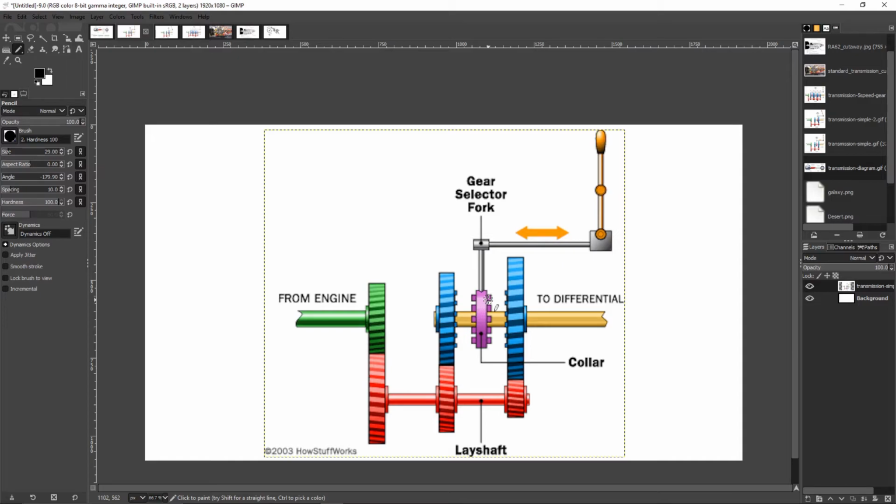The vehicle speed is determining what my output shaft is doing, right? So let's pretend that's this gear here, that's vehicle speed. I really can't change that. I could use the brakes to slow down, and that would change the output shaft speed. Engine speed, if the clutch is fully engaged, is going to determine the RPM of this gear, and I can control that with my accelerator pedal. So in order to get these two to line up, I can rev or let the engine fall in RPM until those are close enough that it will engage smoothly.